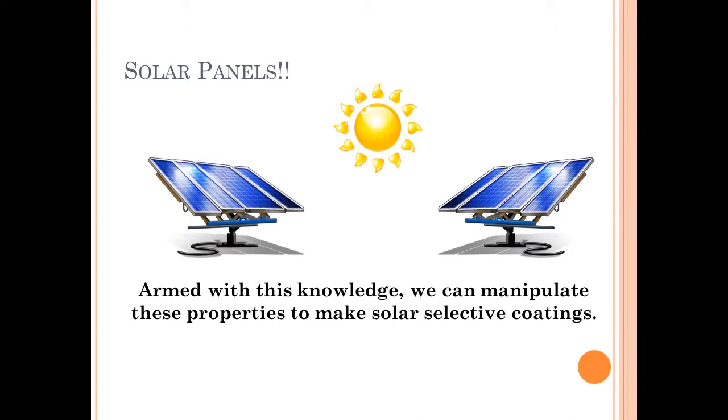An example of this power generation mechanism is a power tower. Power towers use reflective panels to concentrate light at the apex of the tower. A solar selective coating will capture that energy and transmit it to a fluid that can be used to drive a turbine.